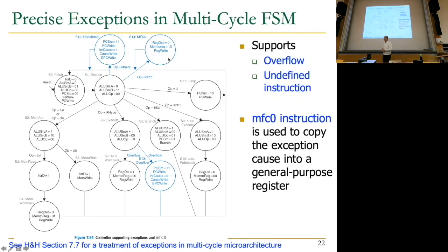Does that make sense? So all of the possible exceptional conditions in your system will need to be encoded in your finite state machine, so that you add these states that take you to the exception handler in a graceful way. Graceful means what we have discussed earlier. You should not update the architectural state with the exception-causing instruction. You should not do this, because there's a problem with the instruction. And you should make sure that you go to the exception handler, which will do some stuff.